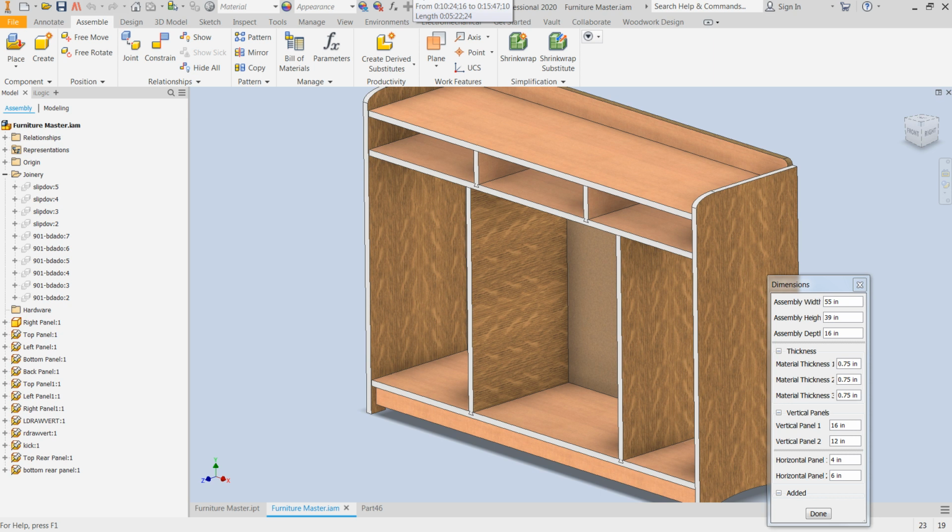So when we start thinking about joinery, okay, we can think of it in the same library way. Okay, what kind of joinery? Is it dowels or biscuits? Is it Confirmat screws? Is it knockdown fittings? And if it is, what does it look like? What do the negative shapes look like? What do the pilot holes look like? Okay, where do you put it? Where is it placed? How do you change it from one to the other?